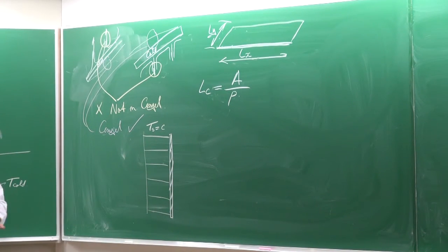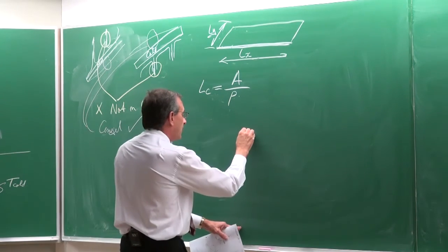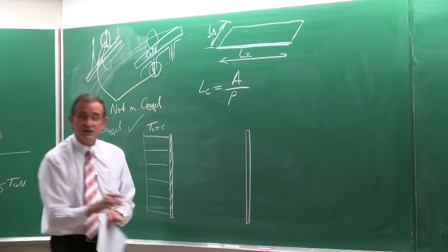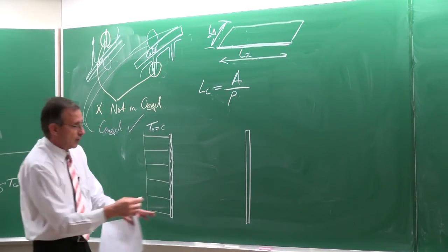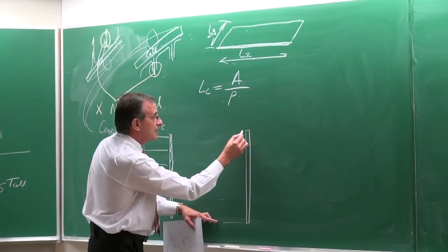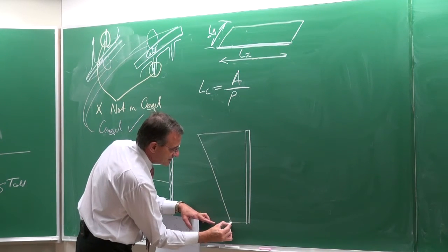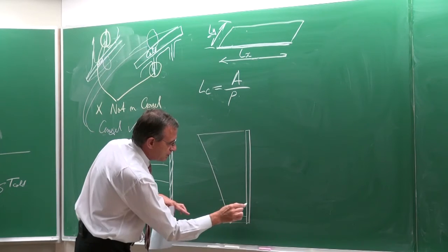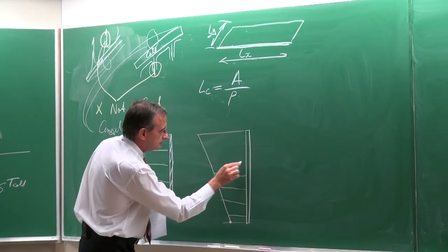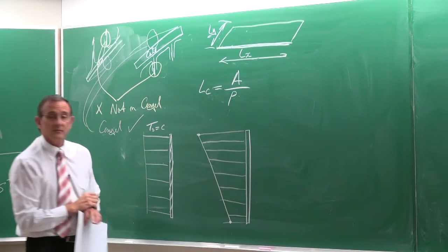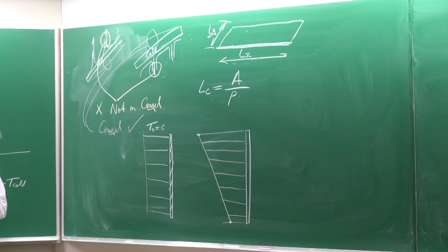In the fine print, it will tell you that for the case where you've got a constant heat flux, that has to be treated differently. For a constant heat flux, your temperature is going to increase linearly, as we've seen previously. So your temperature on the surface is going to do that. Okay? It's going to increase linearly.